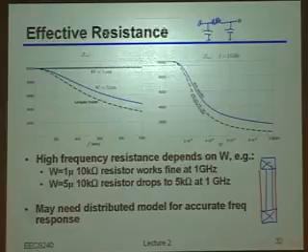If you think about it, this blue version, for the same physical length, has more squares of resistance. Not only that, the parasitic capacitance underneath that structure has a smaller total area, so I have less capacitance. So the red version, which is wider, is going to have more parasitic capacitance for the same resistance.